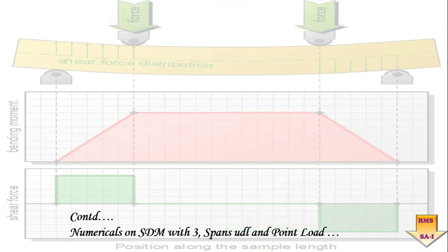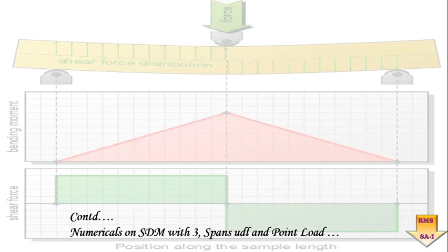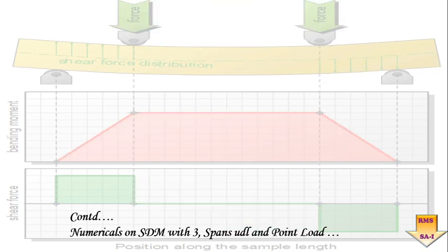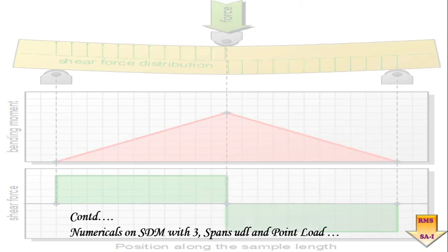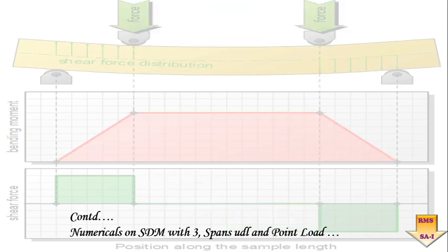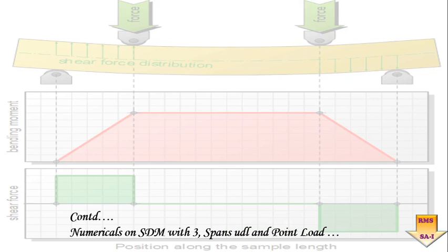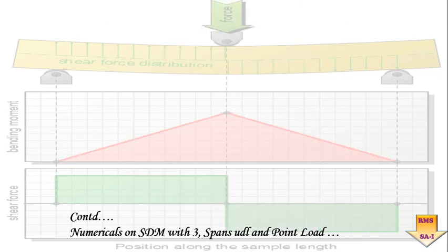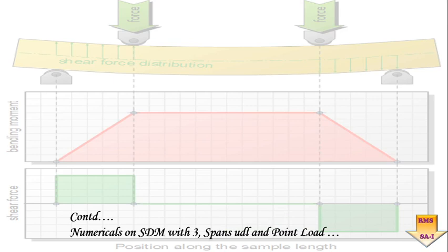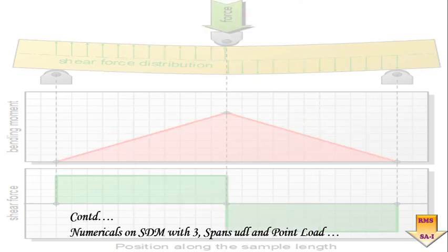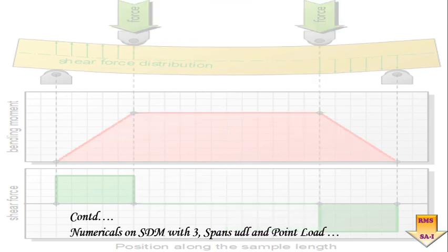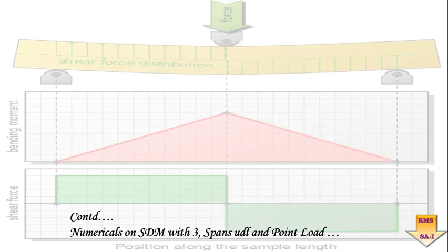As far as the reactions are concerned, how they are to be found out, all this methodology has already been applied in the earlier lectures when we were dealing with the fixed moment. After finding the fixed moment, we used to find the unknowns, that is the reactions, by considering an individual span, showing all the moments, all the loads, all the active and reactive forces, and applying the equilibrium condition. Ultimately we used to get the remaining unknowns in that problem.